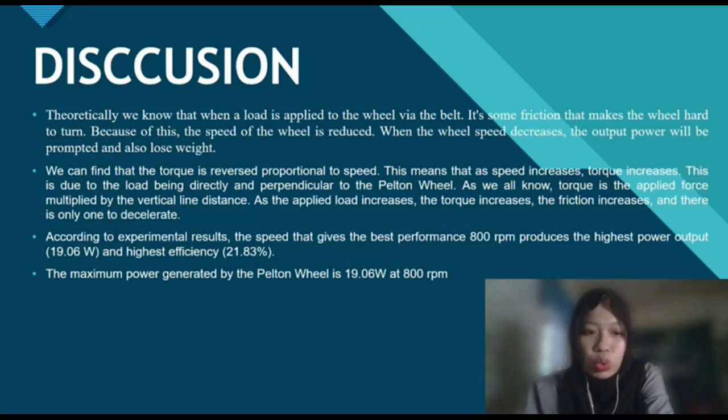This is due to the load being directly perpendicular to the Pelton wheel. As we all know, torque is the applied force multiplied by the perpendicular distance. So as the applied load increases, the torque also increases. The friction increases and so the wheel decelerates.